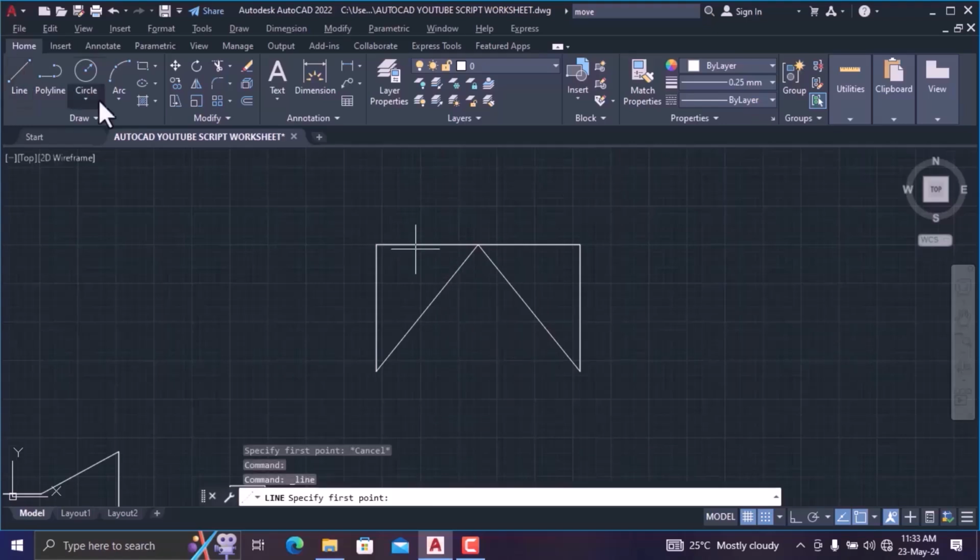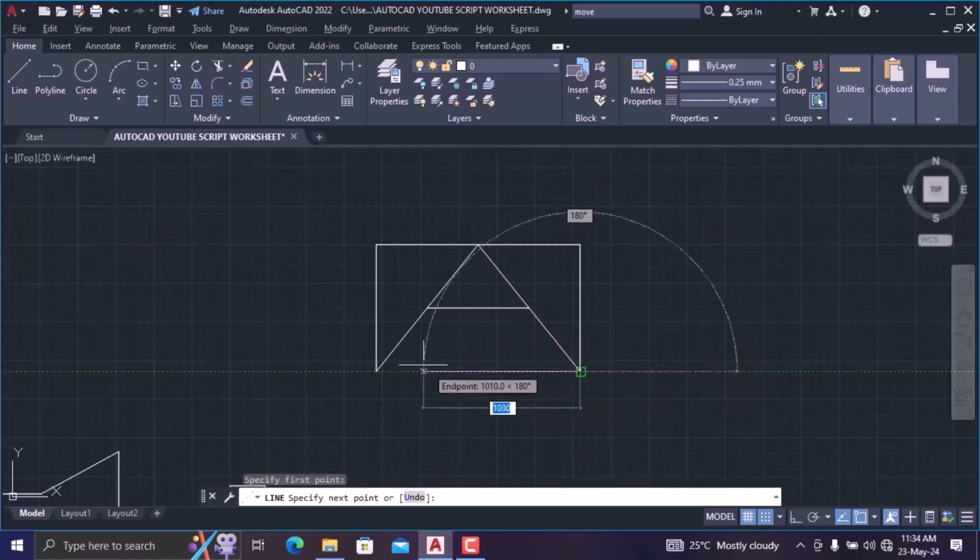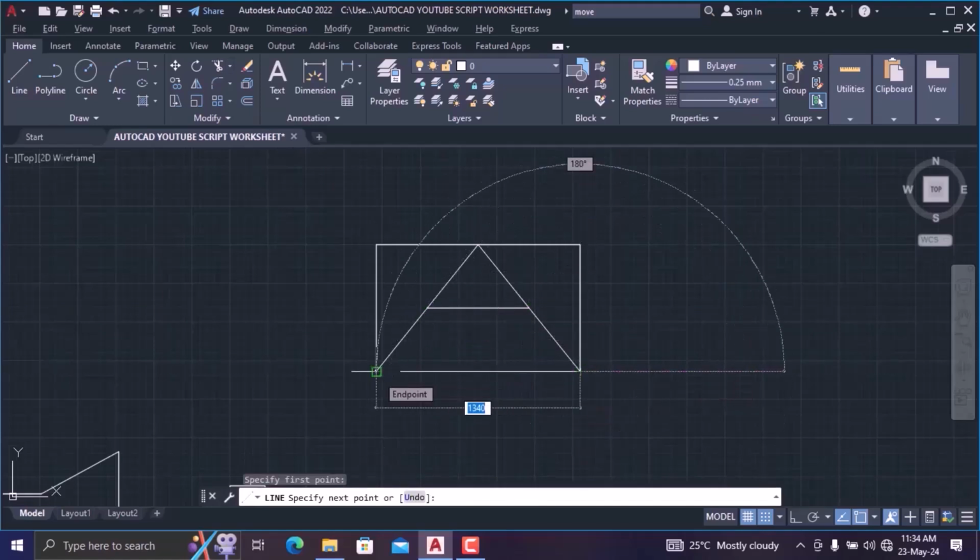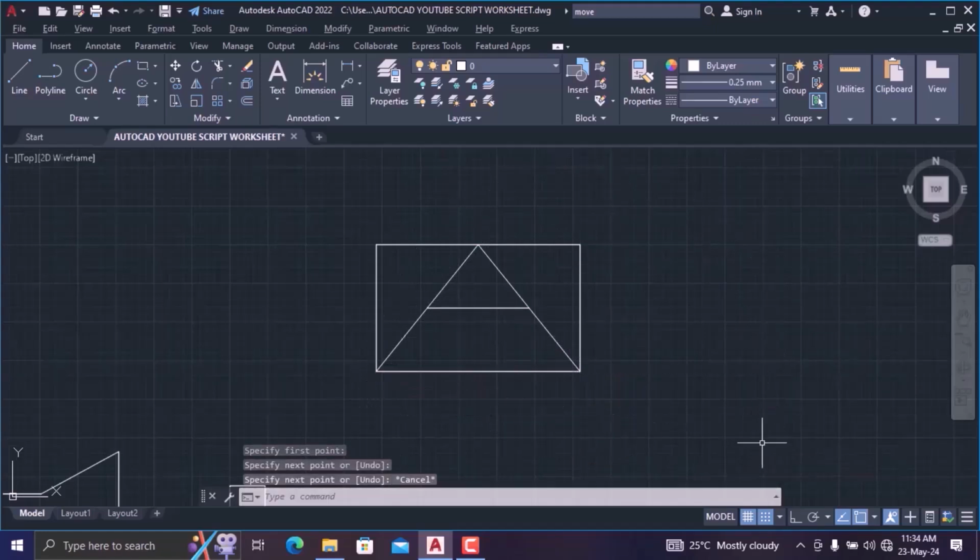I can also go over here, let's say I want to add a line to this midpoint. Notice how it has pointed where my midpoint is, so I can just draw the line. Let's say I want to add this other one too. I also have the midpoint icon showing me. I'll click. Now I want to draw from this endpoint to this endpoint. Notice how it gives me a precise measurement of what I'm drawing. So with this, you could add lines to whatever line you're drawing, and you can also remove a line. To remove a line, you just click on it separately and press delete.